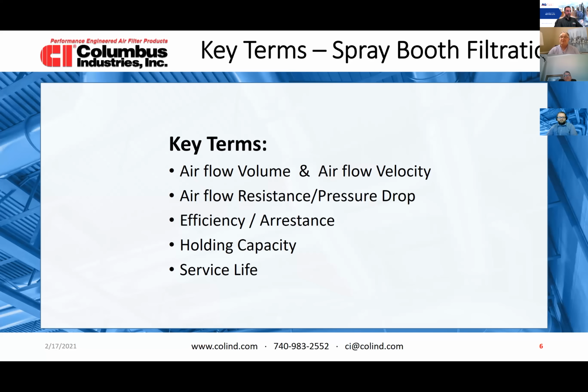Airflow resistance, pressure drop. Anytime we have airflow, if we put an obstacle, and a filter is somewhat an obstacle to that free airflow, it does create pressure. It does create a differential pressure between what's before the filter and what's after the filter.